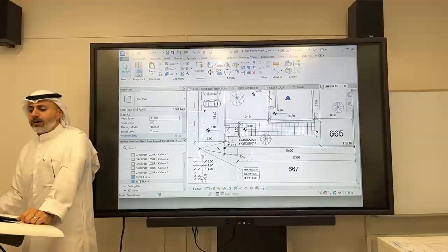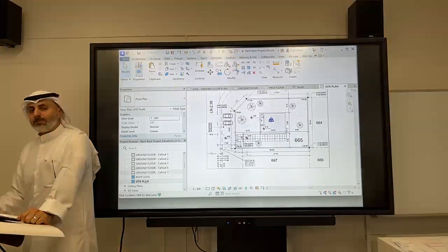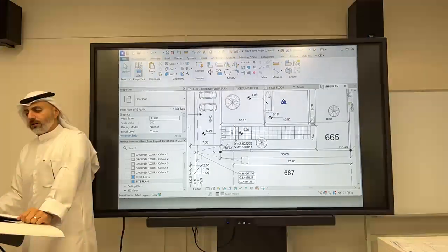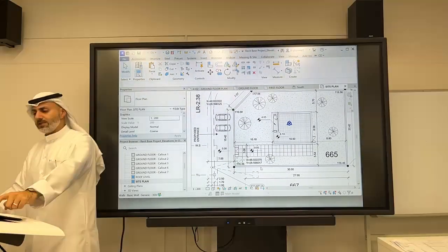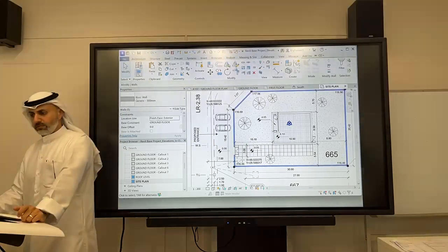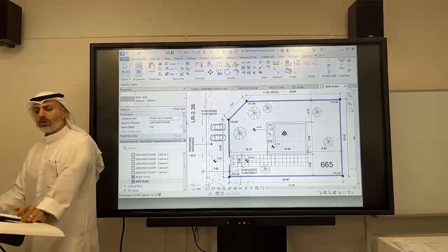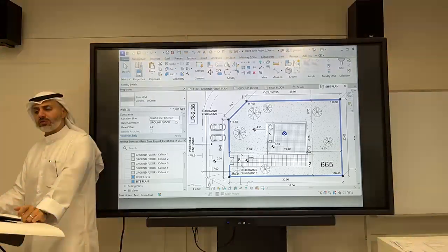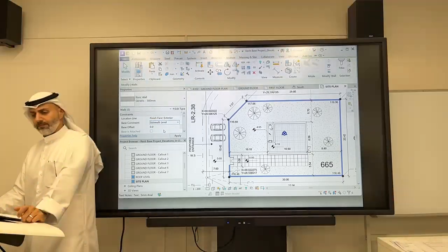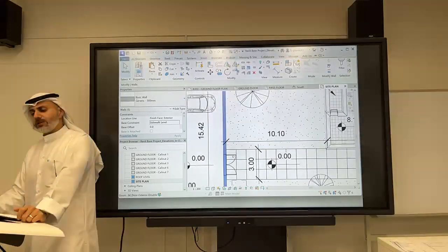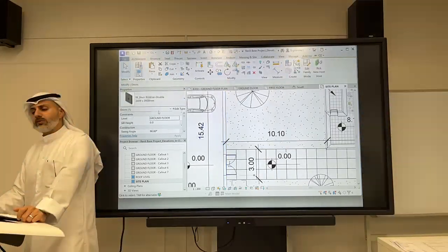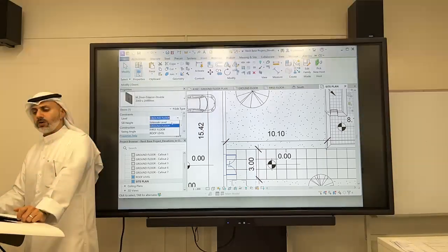Okay, but how do we fix the wall? Go to the site plan, and you can select your boundary wall. So hover over the walls, tab. Now you have all the boundary walls selected, and change the base constraint from ground floor to sidewalk. Make sure to change your door as well, and it's probably already set on the ground floor, so change it to sidewalk as well.